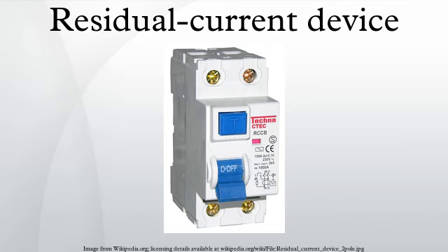South America. Brazil, since NBR 5410, residual current devices and grounding are required for new construction or repair in wet areas, outdoor areas, interior outlets used for external appliances, or in areas where water is more probable like bathrooms and kitchens. See also: arc fault circuit interrupter, earth leakage circuit breaker, insulation monitoring device, domestic AC power plugs and sockets.